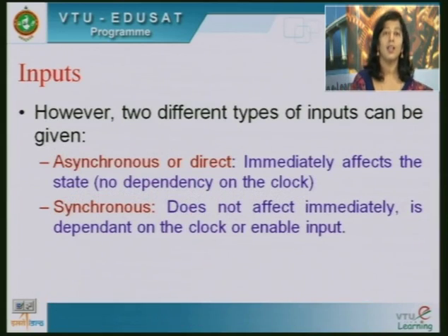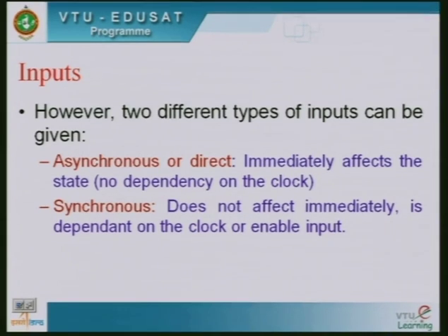So, however, it is possible to give inputs in two different ways. So, next we will design a latch, an extension of this basic element. So, the bistable multivibrator is the fundamental element which is used to make a latch and then a flip-flop. So, now we are going to extend the concept of this bistable element and see how the inputs can be added to this element.